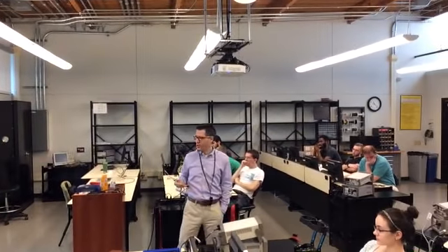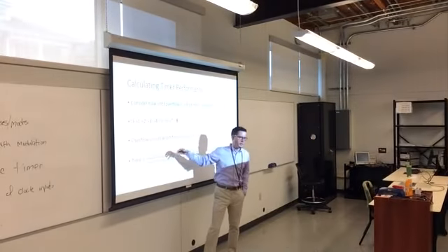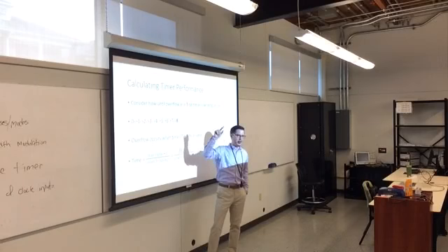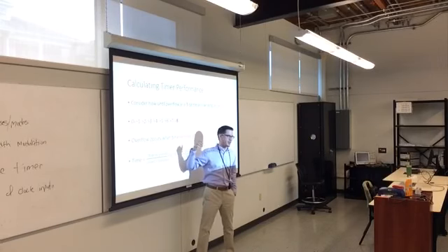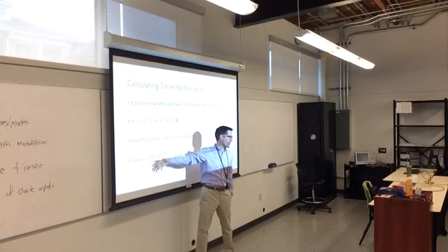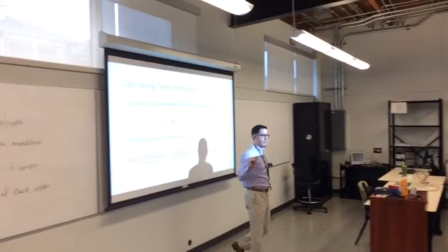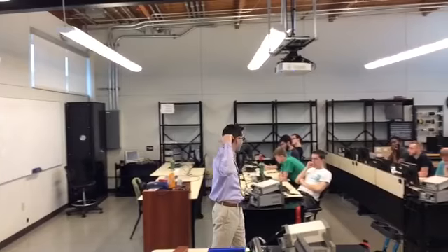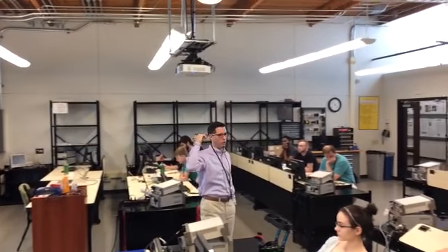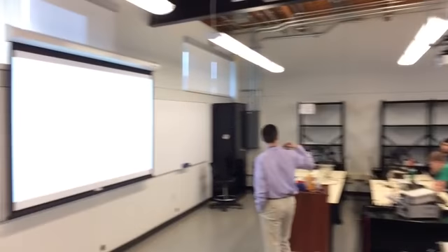Now, it's sort of funny when I say it's the maximum value plus 1, because the maximum value you can hold is 2 to the n minus 1. So this is 2 to the n minus 1 plus 1. So you can also just think it's 2 to the number of bits divided by the frequency. But I leave this in here because when you are loading values in the timer, you're going to actually be putting in a top value, and so that needs to replace that max value location. So you're actually going to put a value in a certain register in the timer, and that's what it's going to be compared to.